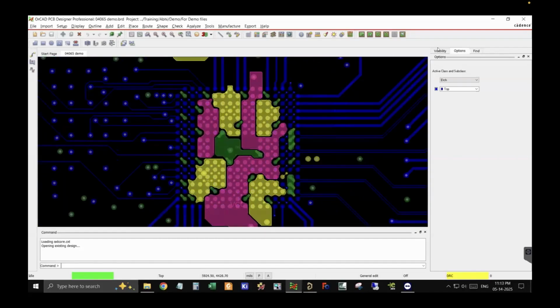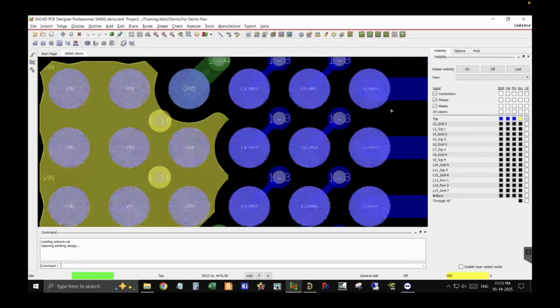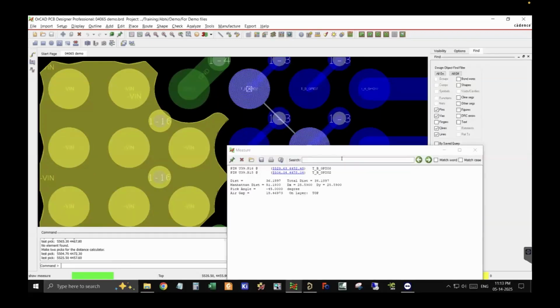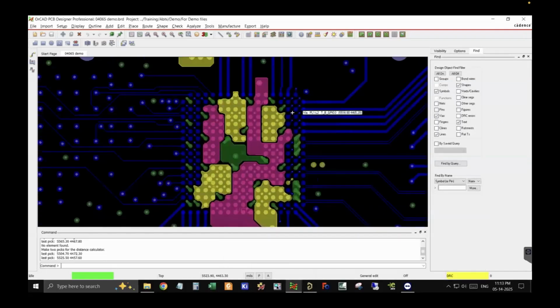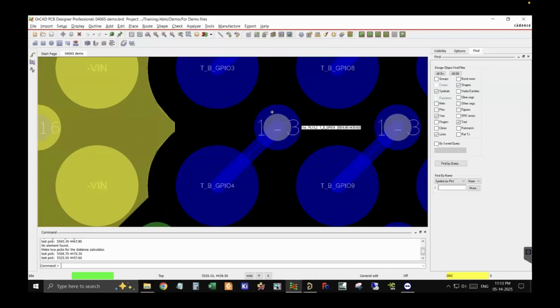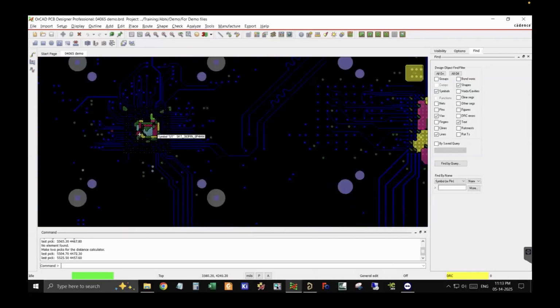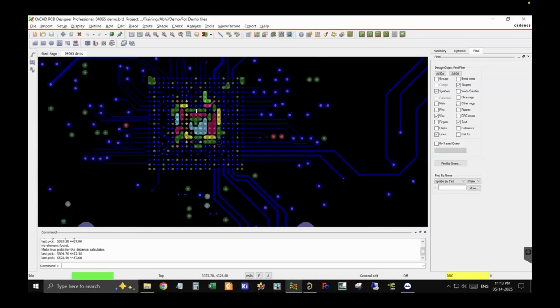As I already mentioned to you over here, they have used blind and buried vias. Because of the spacing between the balls, there is only 18 mils of air gap, so a through via is not possible. And this is a 95 mil thickness PCB, so we would have to use a 10 mil drill. That's why for all the 0.65 mm pitch BGAs, blind and buried vias are used in a stacked manner. Then I'm just focusing on this particular BGA, which is the 0.4 mm pitch BGA.